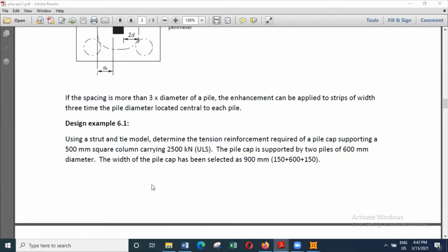So we'll go for an inverted T-type foundation supporting 4 to 5 floors, with bearing capacities varying between 75 to 125 kilonewtons per meter squared, and also different grid arrangements, so that the loads transferred will be different, as will the length of the foundation.